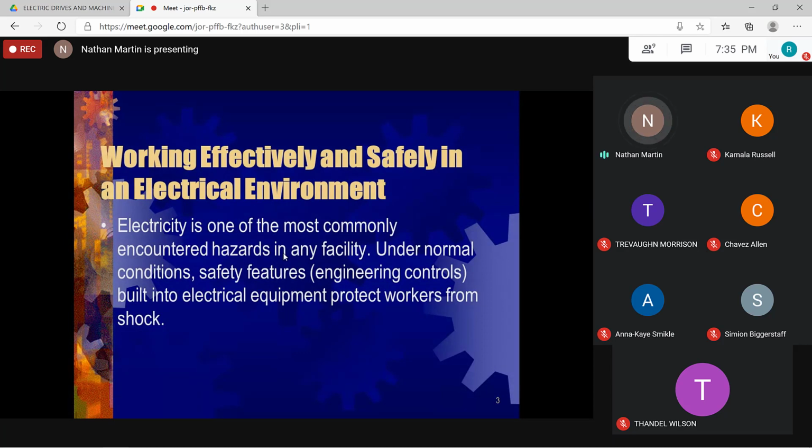They were having some issues at home where they were having low voltage, and they called me to say they measured the voltage in a panel box. The person was getting 95 volts on one leg. It's a 220 supply, and 101 volts on another leg.